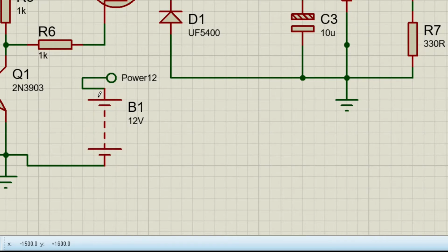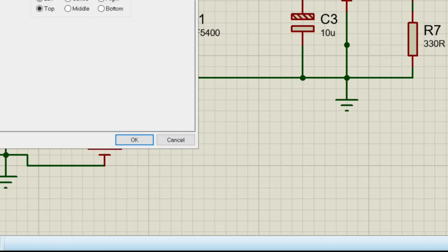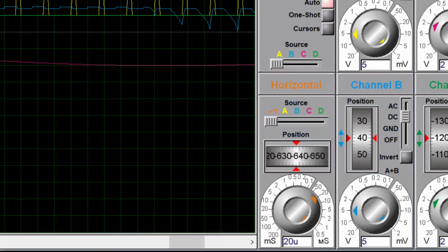So let's say now that we want to switch at 30 kilohertz frequency. This switching frequency you can get from Arduino for the pulse width modulated signals, and let's say that we are using 30 kilohertz now, and for 30 kilohertz you maybe want to use a 20 millihenry inductor, and let's see.